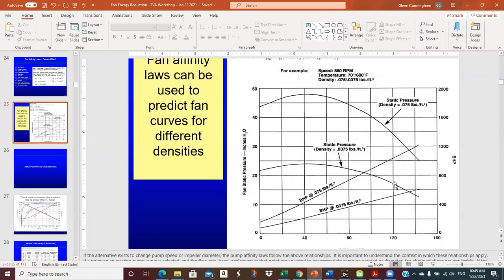In the pictures, I believe it was a discharge damper on a 125 horsepower fan, if I recall. Yep. And you had shown the power cost savings of installing a drive because the discharge damper was in a fixed position that wasn't 100% open.